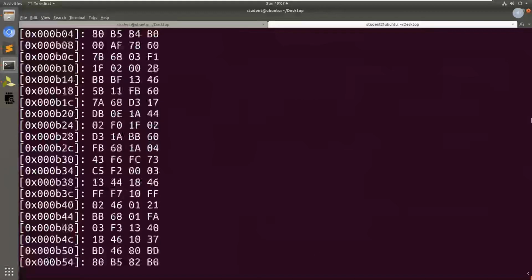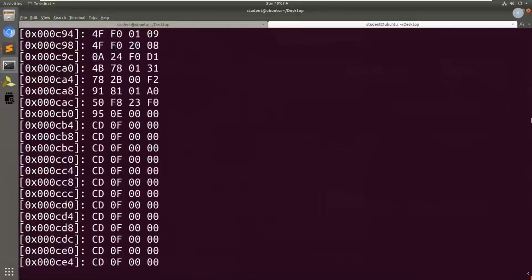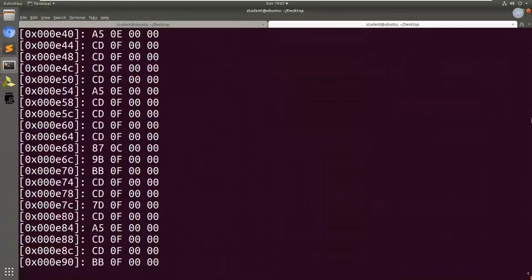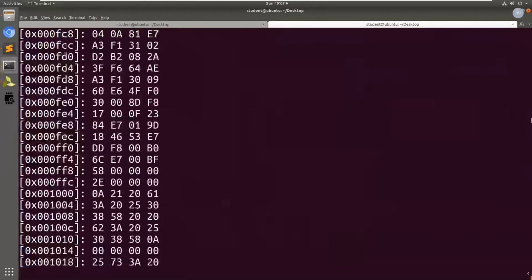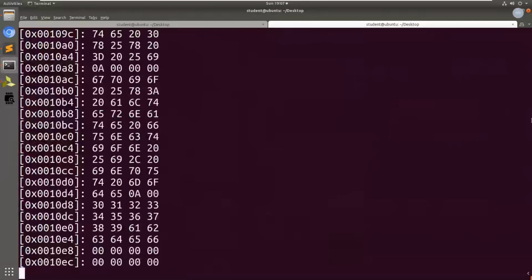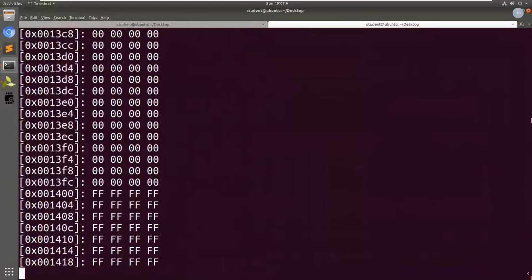So essentially we've done our homework. Now if we ever come across an NXP LPC, and I can tell you from experience, this applies to NXP LPC 17, NXP LPC 13. Basically every NXP LPC is susceptible to this because they all share this low-level code in the boot ROM, and this low-level vulnerability that you can find using, for example, Ghidra to figure out what's going on inside of there.